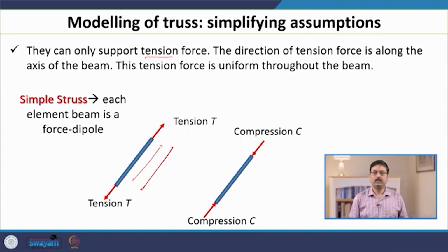But in this case we are going to assume that these beams are perfectly rigid, inflexible. So, the tension force is always along the direction of the beam, because we ignore all those other kinds of internal force and deformation of the beams. And the beam is massless, so it immediately follows that the tension force is uniform throughout the beam.